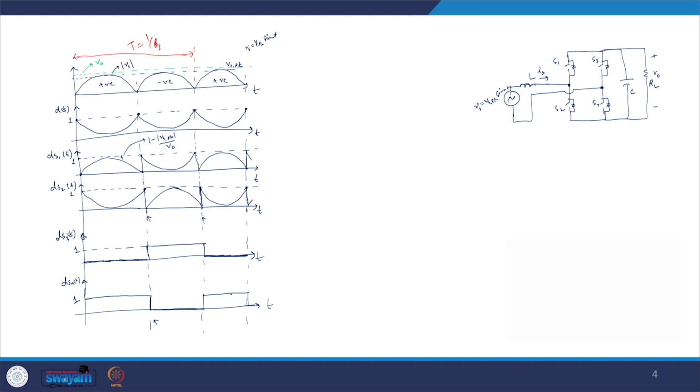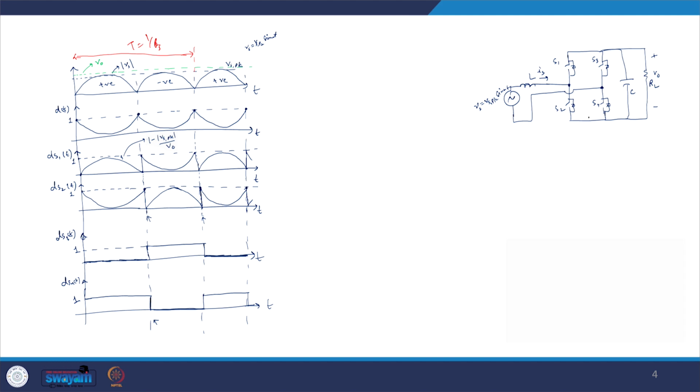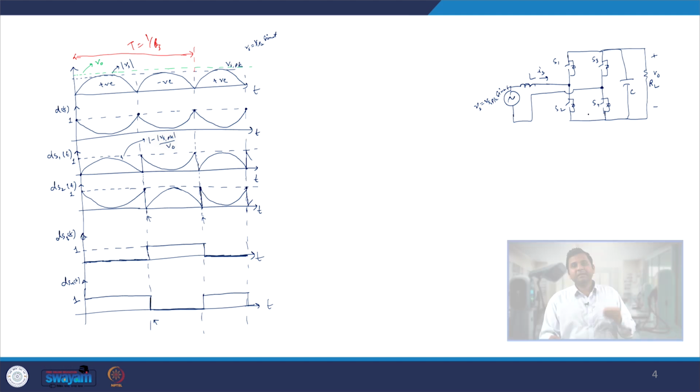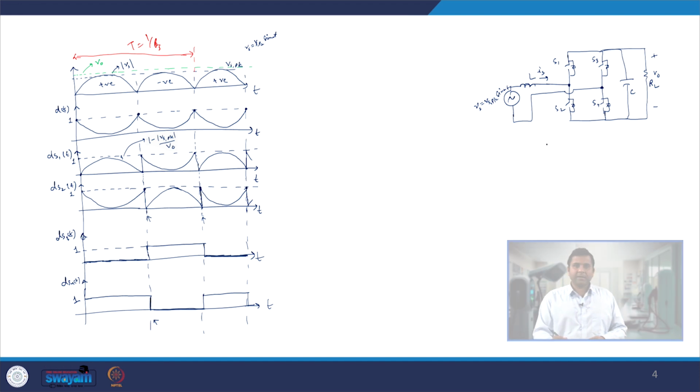And also if we look very carefully, the RMS current of switches in these two legs may be different. That's when you also have to select different devices. When you are selecting different devices, they come with different parasitic capacitances around them, and that's when they will actually have different turn on and turn off times. I mean the transition times during turn on and turn off are different, and that actually leads to the spike in the inductor currents. Now let us see how that spike takes place.